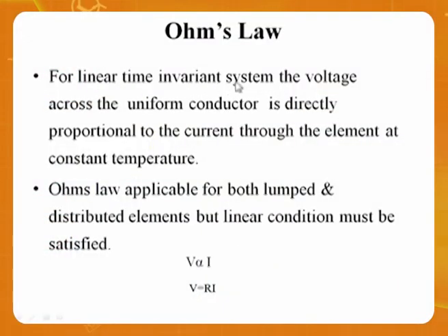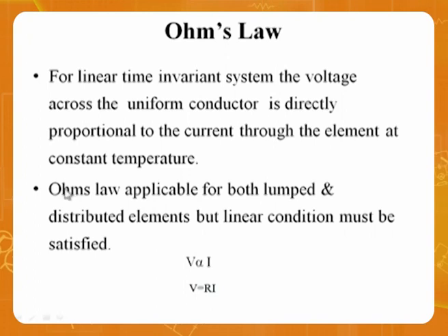That is Ohm's law. Let me define Ohm's law. For a linear time invariant system, the voltage across a uniform conductor is directly proportional to the current through the element at constant temperature. Please remember these three words I have made very interestingly. For example, Ohm's law is applicable for both lumped and distributed elements, but the linear condition must be satisfied. The word linearity is a must.